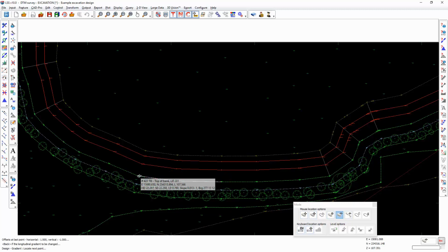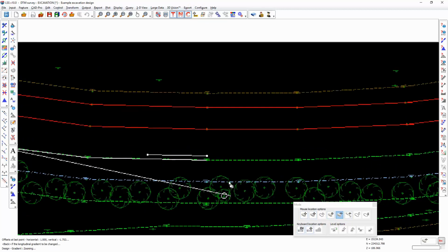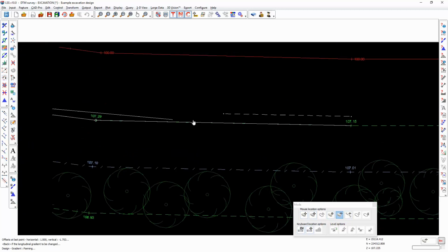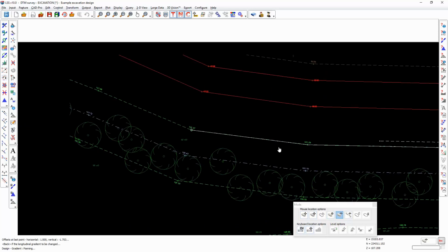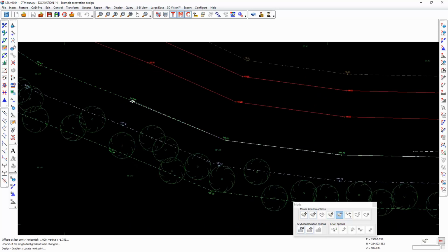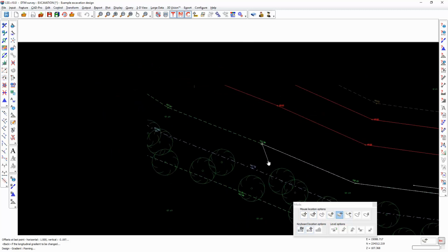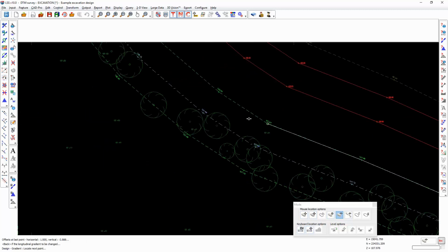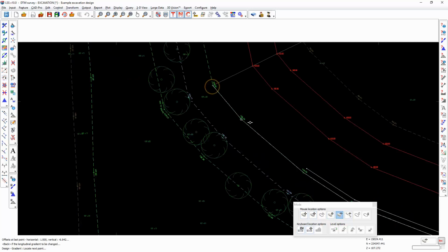and as soon as I digitize the third point, I'll turn off the active cursor, and you will see the beginning of the design. That first point is 1 meter offset horizontally and 1 meter offset vertically, and it will always be one stage behind because it doesn't know where I'm going next, so it can't create the corners until I've gone round that corner. This line is just remaining parallel. Now that's maybe not what you want. Escape